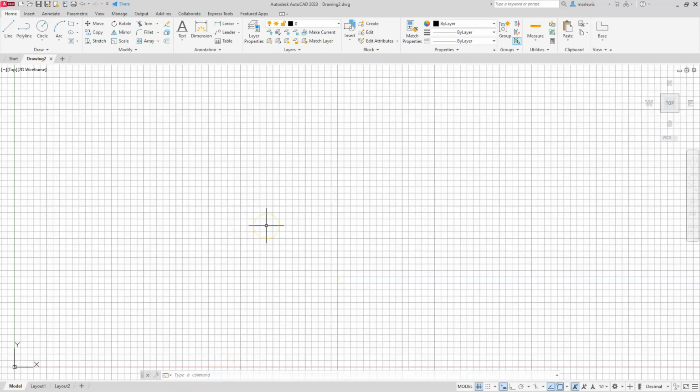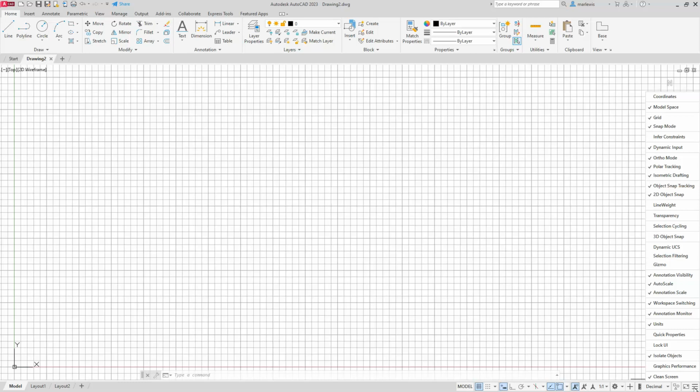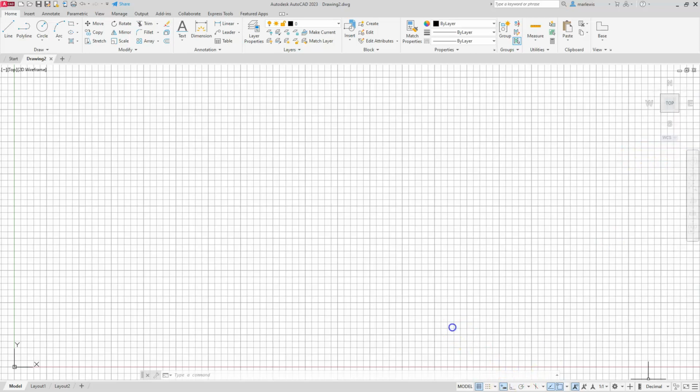Alright, and I discussed that the command line is going to be either here or right next to your cursor. We'll take a look and see how that's done. The last thing I'm going to do is take a look at the quick access panel. Remember that I told you in the previous lecture that this dynamic input is probably turned off on yours. If you want to turn it on, you're going to come down to the 3 customization bars. Here it's going to open up the fly out, and then you're going to click on this box and it's going to put a check in front of it. Once you do that, you should have that icon there.